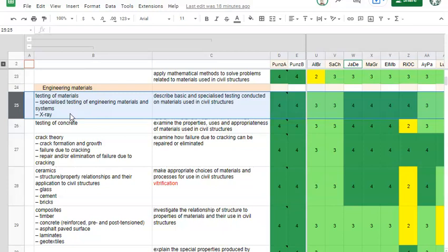Now, we also have specialty tests for concrete like slump tests, right? We've talked about these and that they're used for checking the workability of materials. Engineers who are working in labs, or scientists, use transverse beam tests where they make a concrete beam and they test it under real world conditions, right? But in a lab. So they're the main concrete tests.